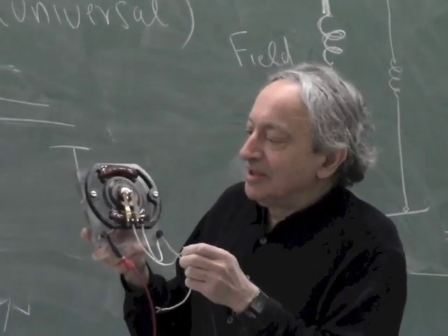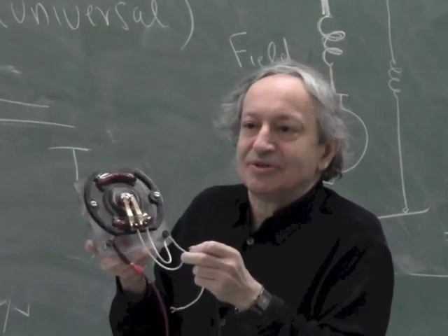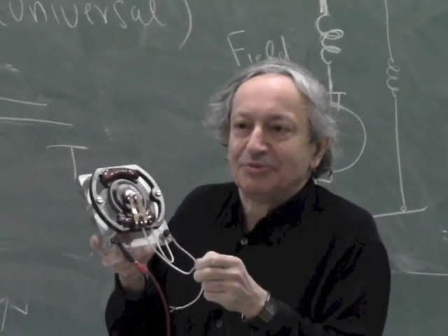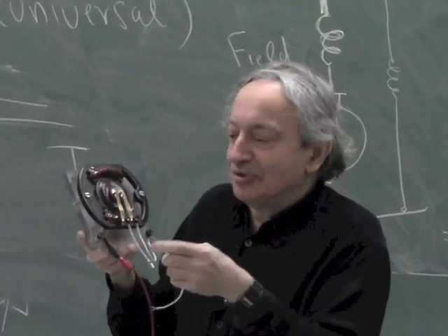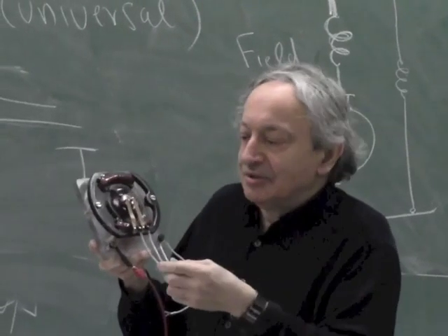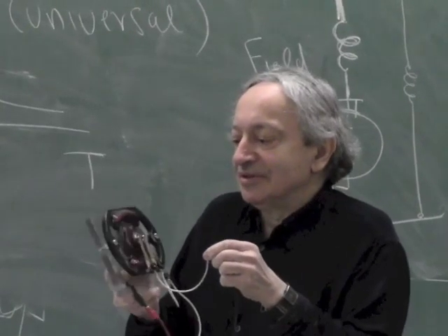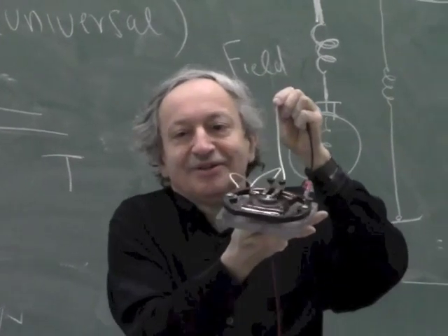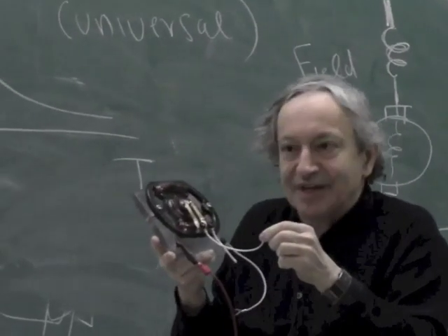Okay, so what limits it here, it's not going that fast, not so much because of air friction, but because of mechanical friction. I mean, that's quite an inefficient motor because it has big air gaps. So what's limiting the top speed is mechanical friction. All that you see is bigger sparking. I don't know if you can see sparking, but it still doesn't run that fast, okay?